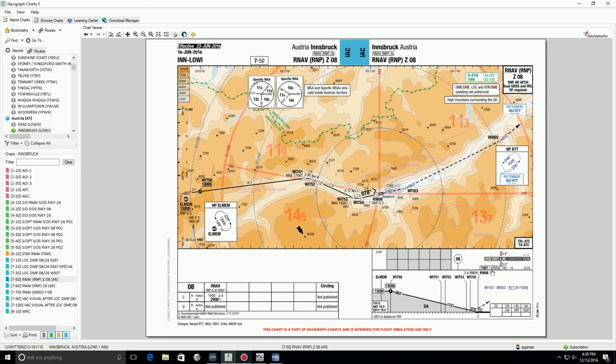The runway itself, we see that we have 1,900 meters available, 45 meters wide, and the PAPI angle is 3.5 degrees. So let's see if we can do that. What we need here is the minimum is 2,900 feet and RNP 0.3. So this is what we will do. 0.3, we have to set the system.